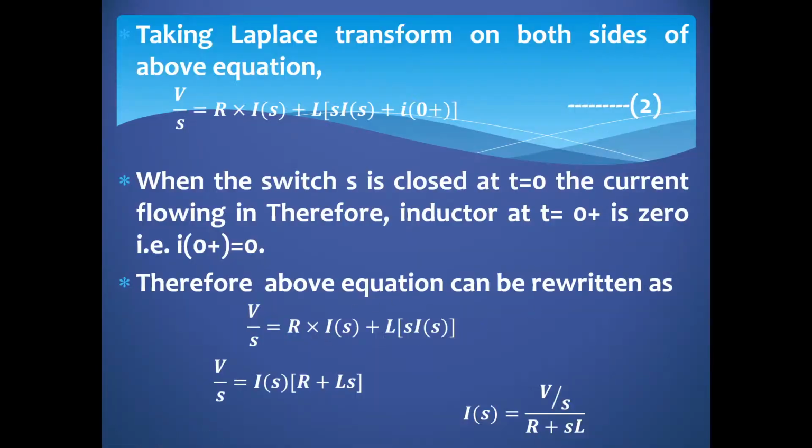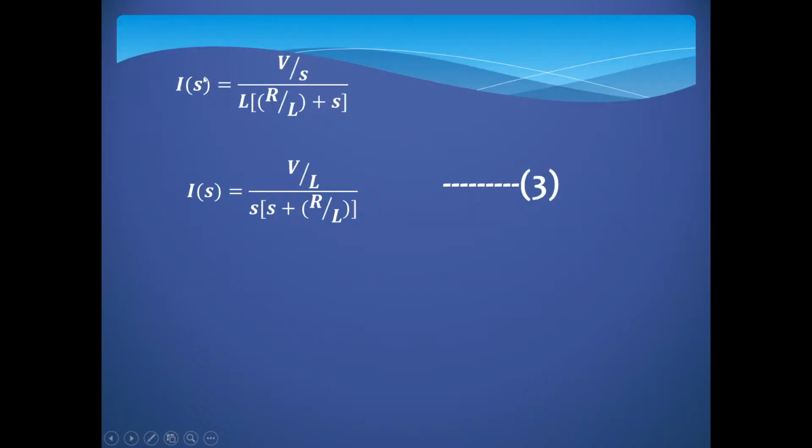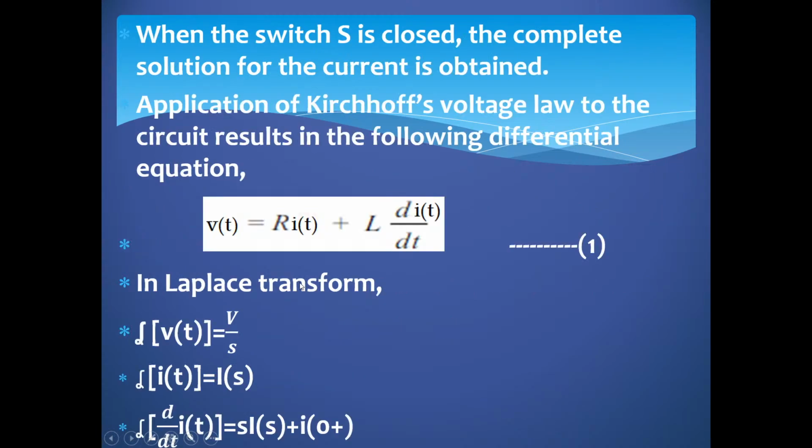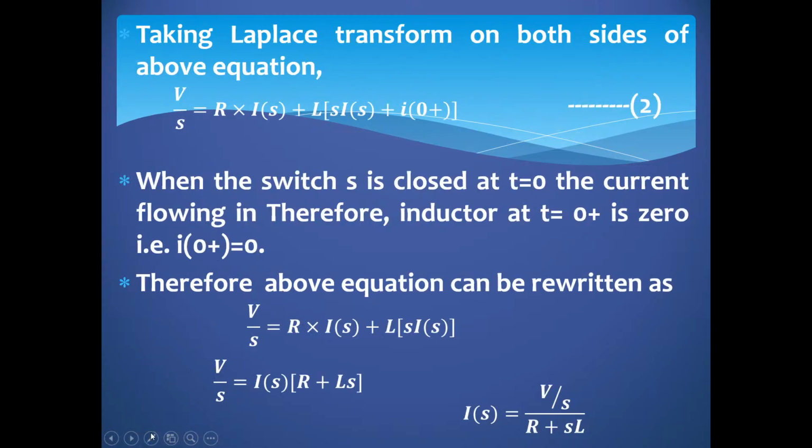It was my mistake. Actually the inductor acts as an open circuit as soon as the switch closes, but I was telling you that it acts as a short circuit. I hope you have written this. What you have to write here is simply that, taking the Laplace transform, you will get this equation. This equation you have to write.